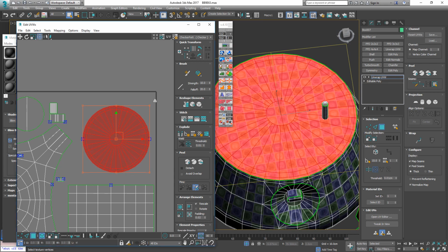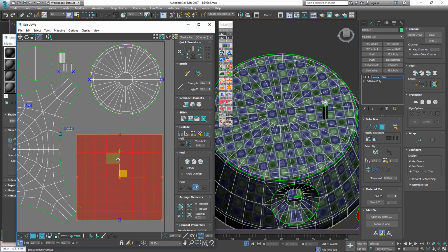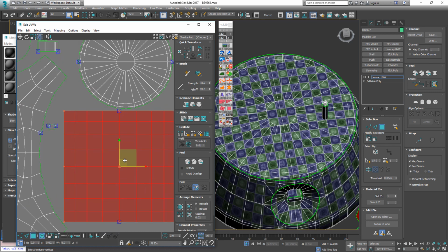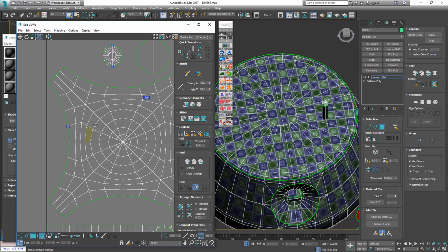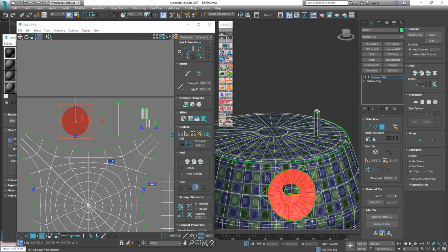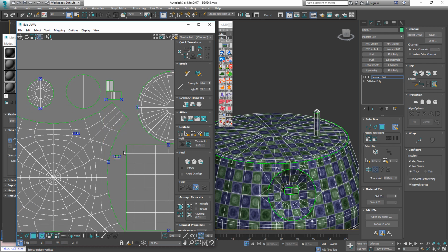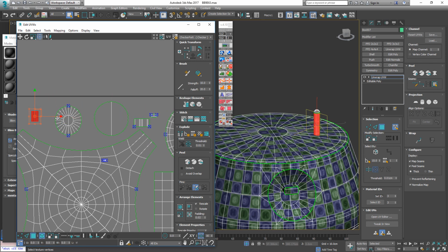For example, we can scale that here up a little bit, that top piece, and we can bring that up here a little bit and just make sure that nothing is intersecting here within our UV shells. And that piece here, the camera eye, we can also bring it up a bit. The further you scale it up, the more resolution we have available on it. But you don't want to scale it up too much so that it gets way more high-res than the other parts.